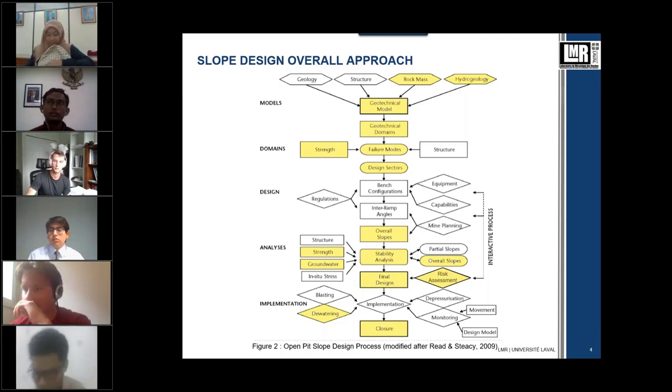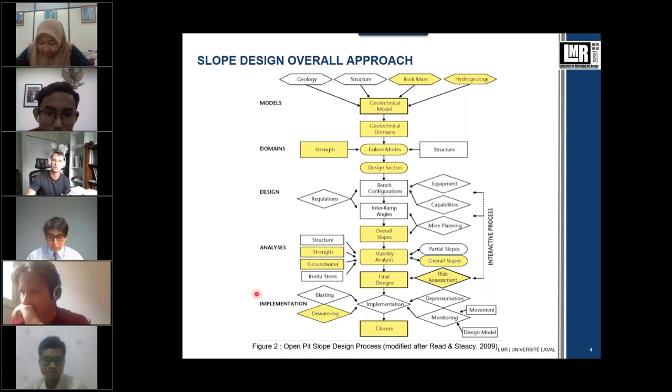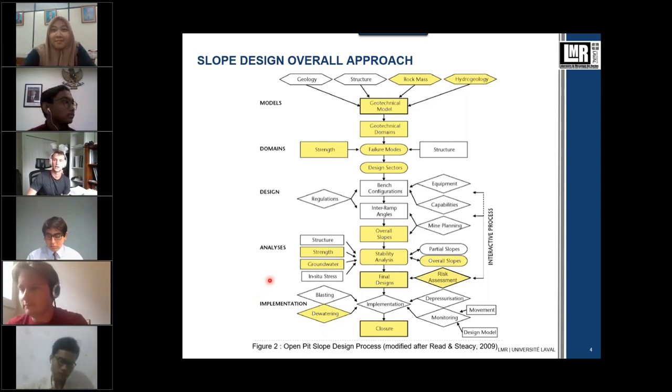The deterministic approach, based on the mean rock mass properties, allows calculating a factor of safety using the 2D numerical modeling code FLAC Slope. The probability of failure and the mean factor of safety were calculated using a Monte Carlo probabilistic approach using statistical distributions of the rock mass shear strength parameters. The 2D numerical modeling code RS2 was used for the probabilistic approach, and the results were compared with FLAC Slope for the deterministic factor of safety.